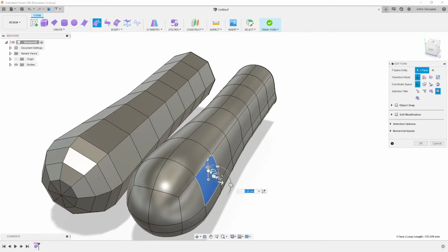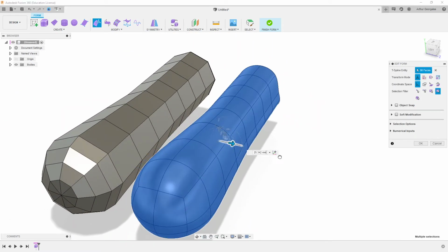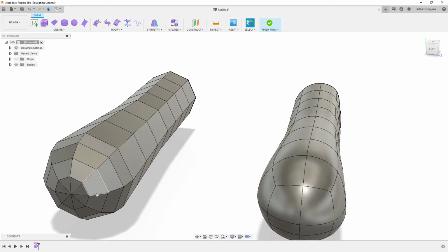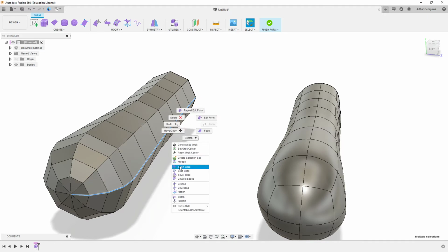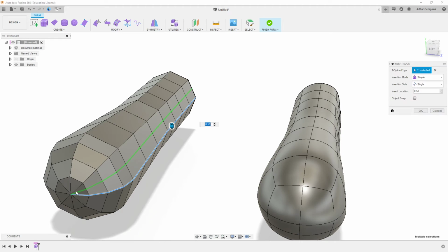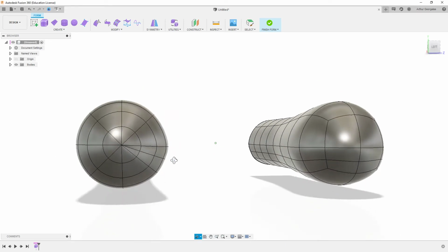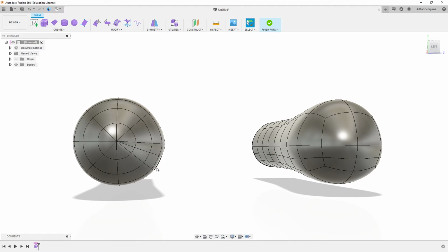In CAD class, we're working on game controllers where that's super useful. On this, however, if we double click to select the loop, it only goes from here to here because it doesn't continue, it all ends up in a point. So when we add in another line here, you can already see it's losing a lot of its roundness.